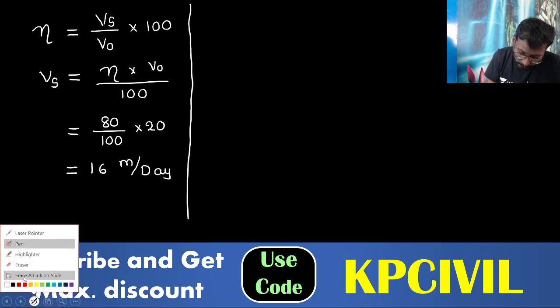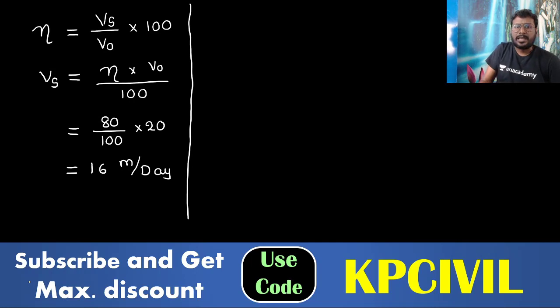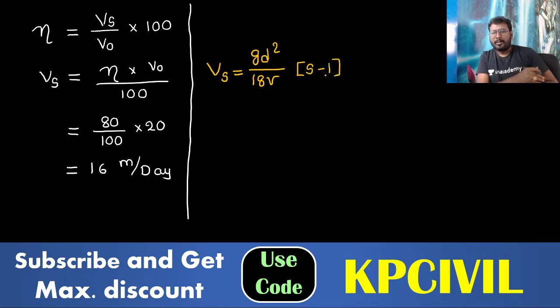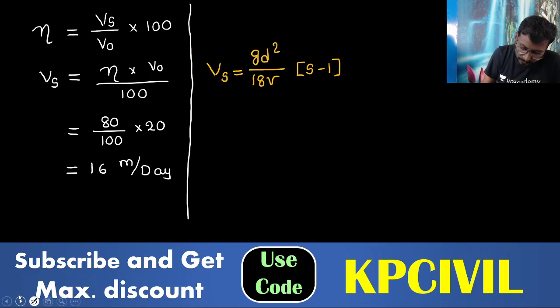And we have the formula for settling velocity because we need the particle diameter. We are taking the formula for settling velocity according to the Stokes velocity equation: Vs is equal to g D square by 18 nu into S minus 1.